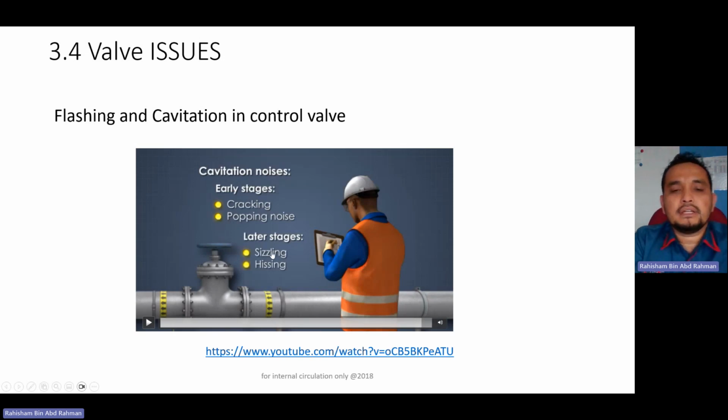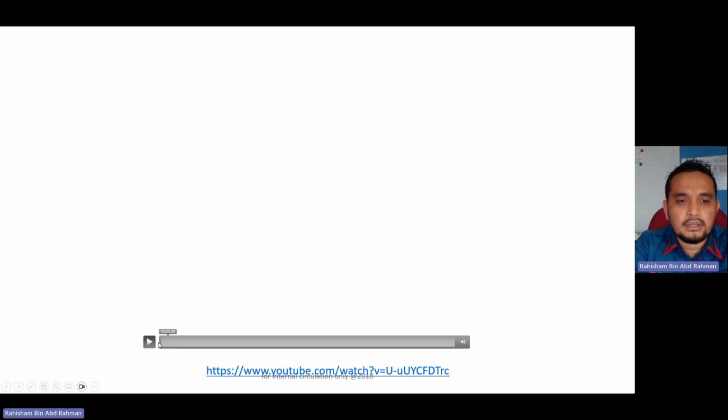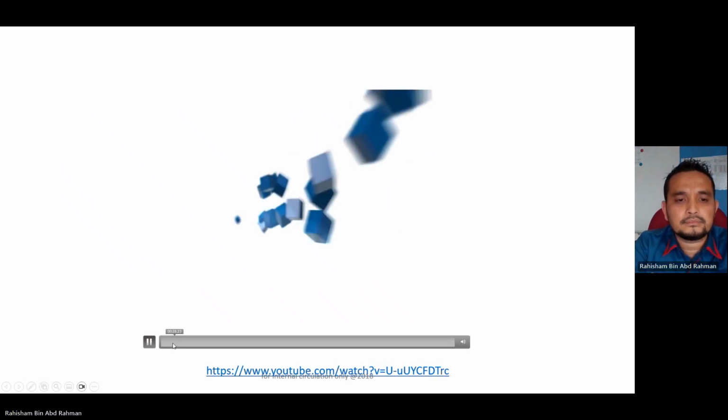But at the severe stage, you will hear a sizzling effect or hissing sound around the pipeline, around the valve area. That is the indication of flashing and cavitation, right? So we have another video here. Let's watch, or maybe I'll just skip where possible. Sorry. Okay, we have another video.